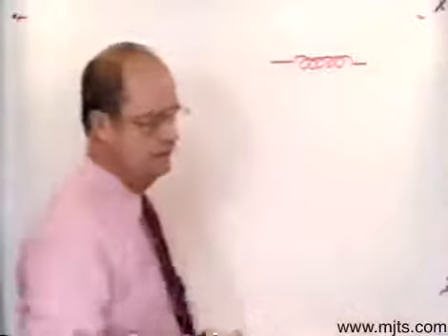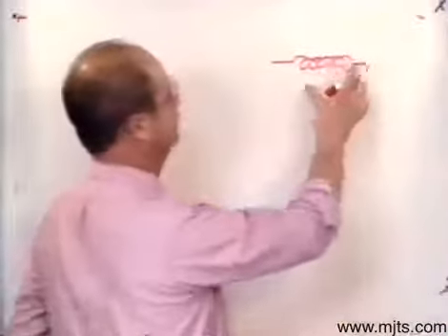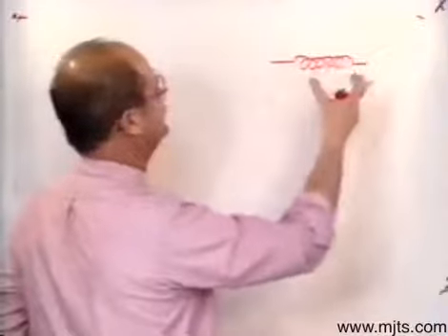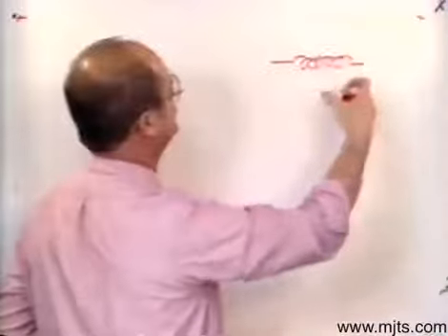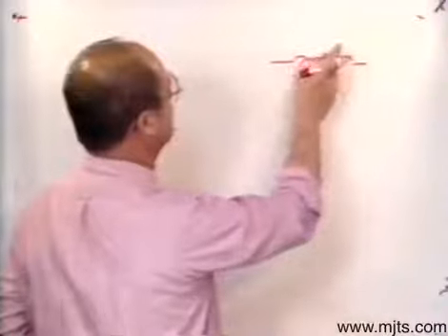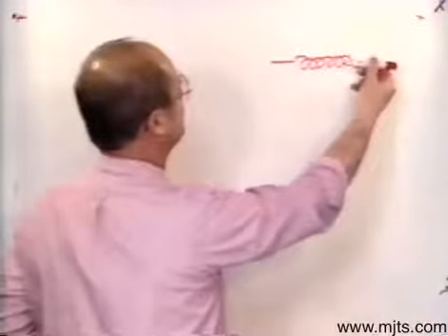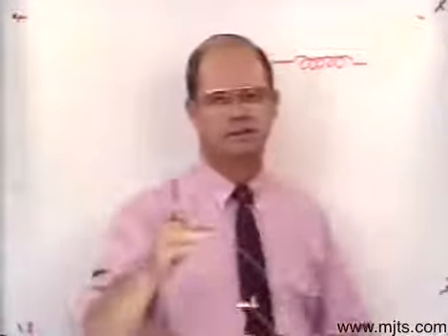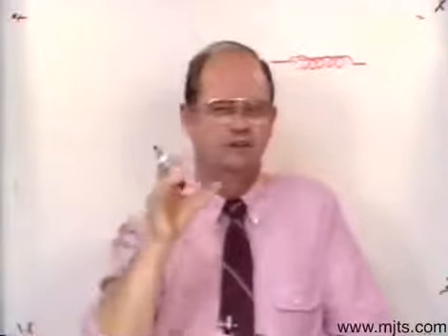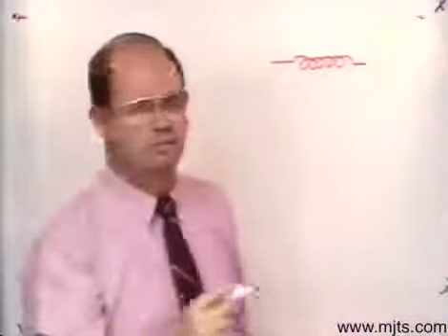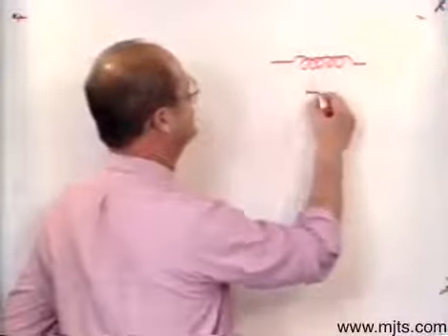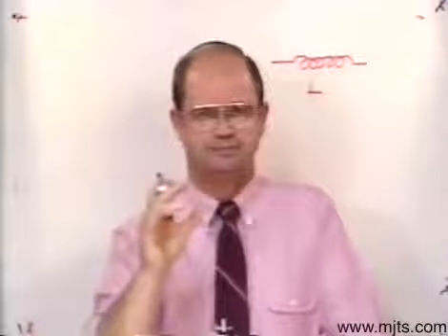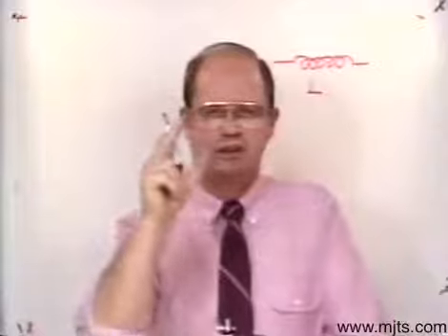The value of that inductor can be changed. I can increase my number of turns, I can make the turns more compact, I can stick a piece of iron in there that'll concentrate the flux rate within that inductor. All of those variables will increase the value of that inductor. The symbol that we're going to use for an inductor is L. Remember, we use R for a resistor. Now for an inductor we're going to use L. Now the unit of measure of that inductance is going to be a Henry.